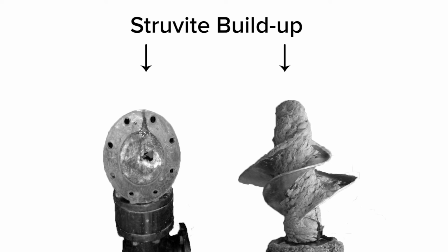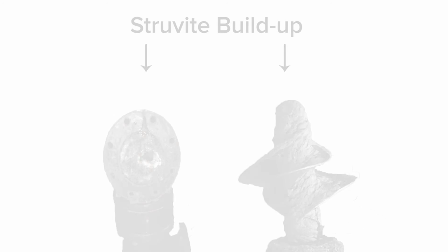secondary market. For plants that have problems with struvite buildup in the digester, one step that can be added is to promote the release of that phosphorus prior to the digesters, and send that phosphorus directly to the fluidized bed reactor and bypass the digesters completely.